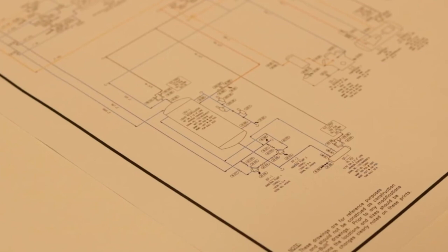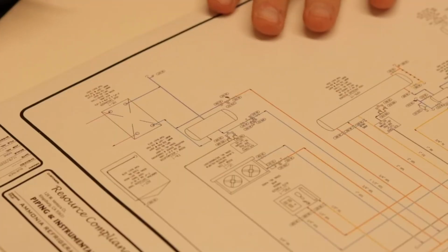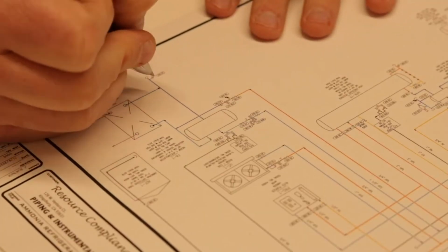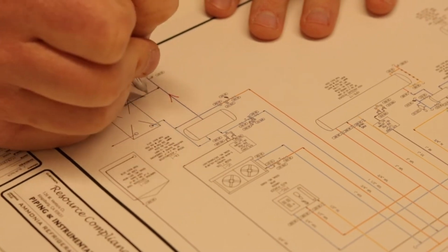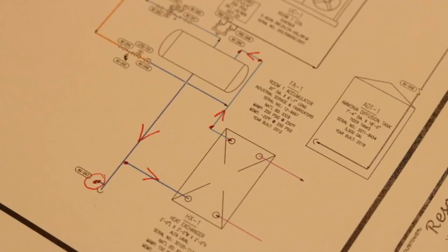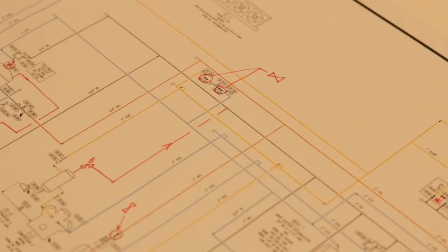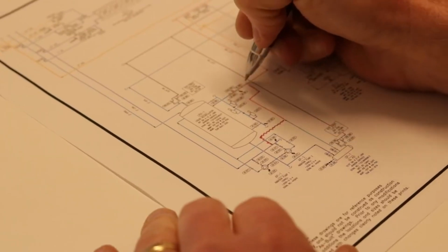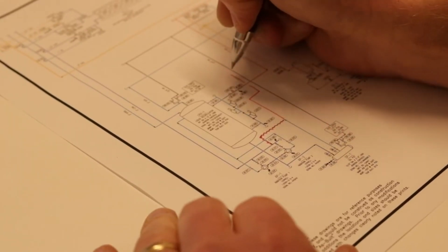Create a modified P&ID of your system that incorporates inaccuracies. Assign an operator the responsibility of auditing the P&ID and see how many of the errors he can discover. Examples of modifications that can be made are reverse some flow direction arrows, remove valves, move pipeline connection points, rename components.